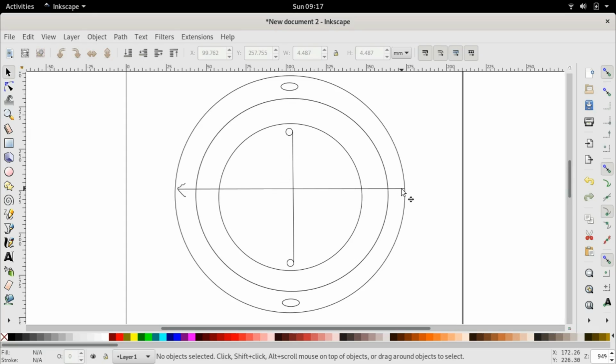Now, if we do that, we see that the stator flux is passing through the rotor. This stator flux passing through the rotor has maximum linkage with the rotor. The entire stator flux is being linked with the rotor. Of course, as always, there will be some leakage. We can never avoid that. But barring the leakage, all the stator flux is linking with the rotor.